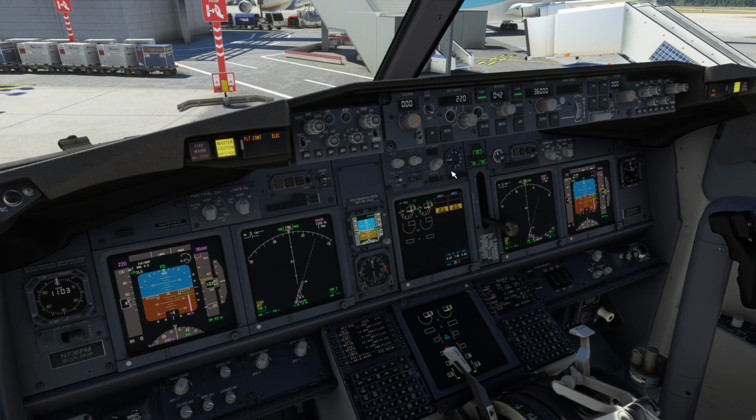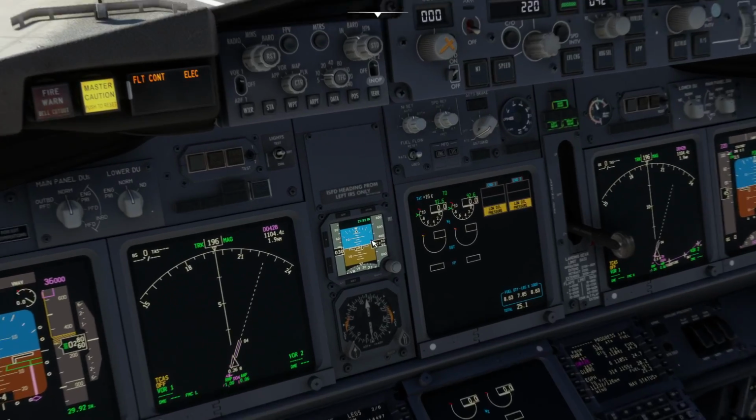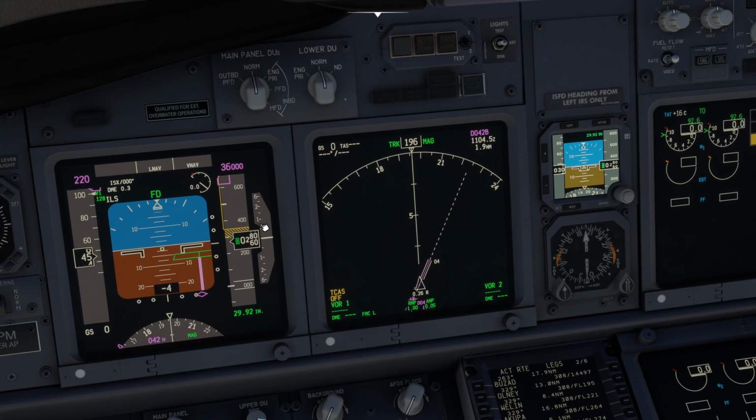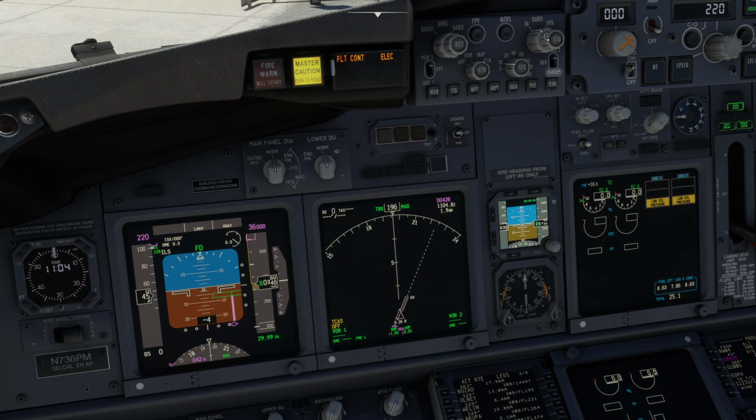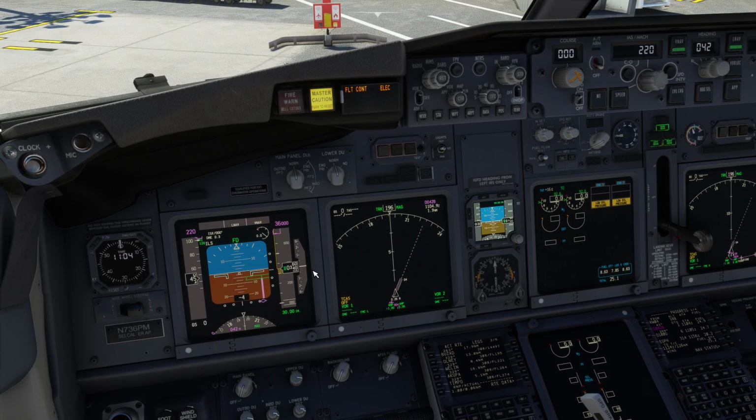The other thing we need to do is calibrate the altitude, or the barometric pressure. The altitude works by reading the air pressure outside the aircraft. If we press B, it shortcuts it. If you haven't got a keyboard, you can roll the knob on the barometric pressure up here and you'll see this changing. So you can dial it in, but I can press B because I've got a keyboard plugged in and it shortcuts doing that for you.